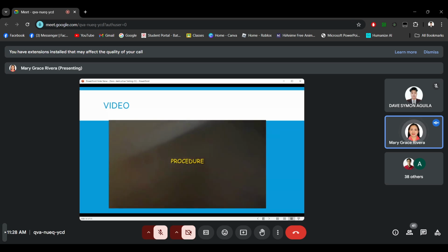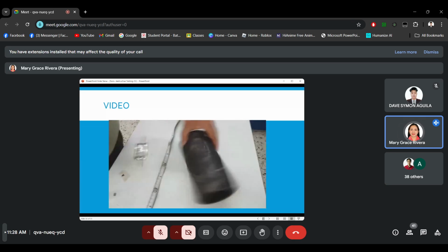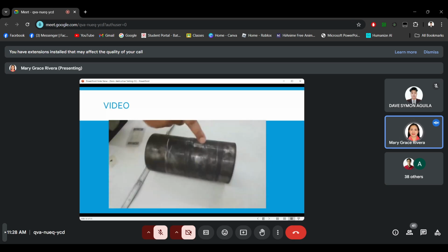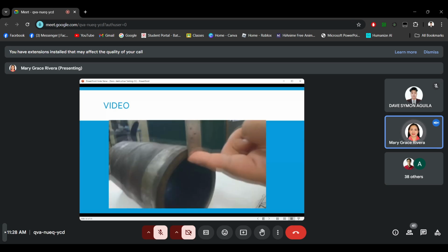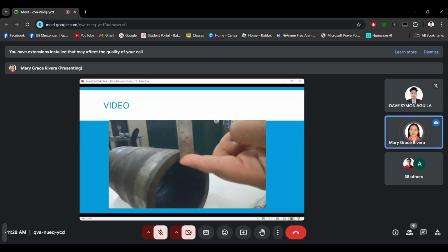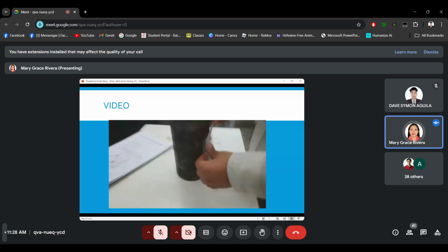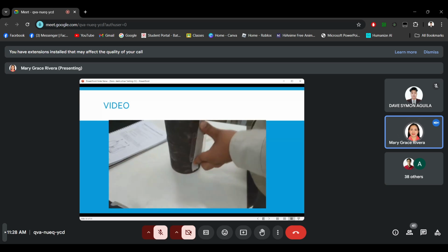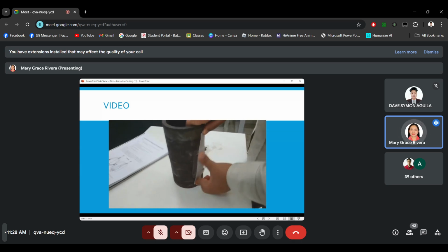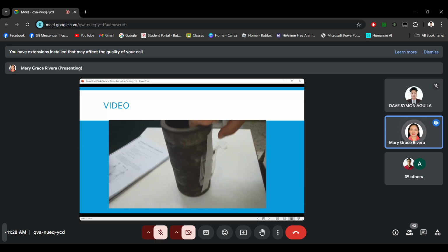The procedure is, after finishing film loading, start to perform this technique with visual inspection of the specimen. Examine the welded specimen visually and note down any surface defects. Choose the appropriate IQI type according to the sample thickness, of the same material as that of the specimen. IQI should be placed in a proper manner on the specimen, i.e. source side and wires across the weld.